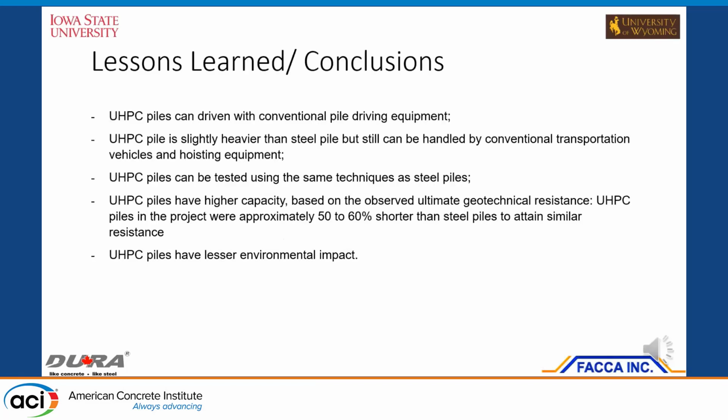So here are some lessons learned. UHPC piles can be driven with conventional pile driving equipment. They are slightly heavier than steel piles, but can still be handled conventionally in terms of transportation and hoisting equipment. It's the same techniques as the steel piles, tested.